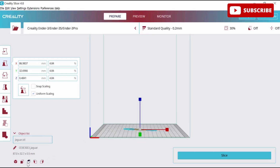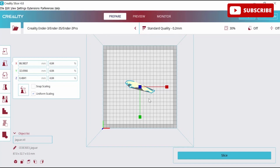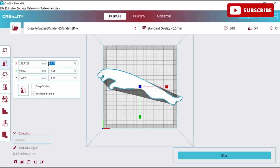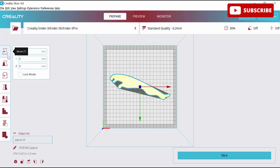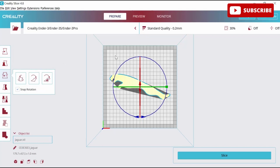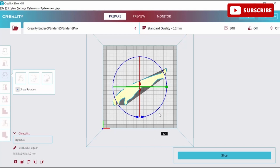We will scale it so that it should come on our build plate size area. So let's go to a different viewpoint so that it will help us to scale it properly, so that we can utilize the max for the printing purpose. So here we can change the number directly. So let's put over here 10, and yes, we can see that this has properly come inside the build plate area, but still I want to change the rotation. So to change the rotation, I will just use the rotate, and with the help of this particular arrow I will change the rotation so that I can align it diagonally.